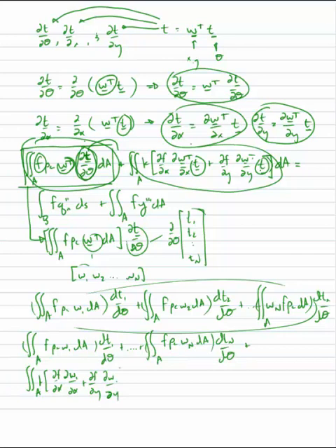And then we have these last two terms that just come to the other side. So the integral over the boundary of the heat flux normal to the boundary times F times dS, plus the integral over the area times F times g triple prime dA equals 0. So that's what we have after substituting in our form for the unknown temperatures.